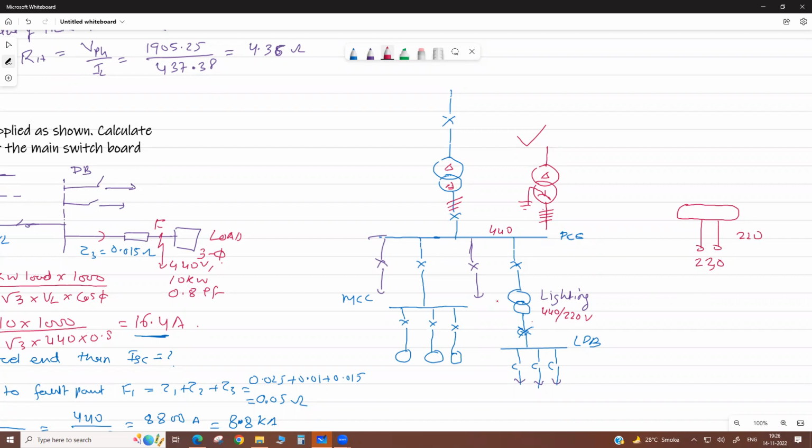Second, there is a percentage impedance of this also, like 10%. So if we check here, what is the fault level here? Maybe in main distribution it is like 50 kiloampere short circuit. But in the lighting circuit only 10k. Because you know these are MCBs. You have lighting MCBs like 6 ampere, 10 ampere. Okay, this is the rated current. But there is a short circuit rating also written, like 10k.